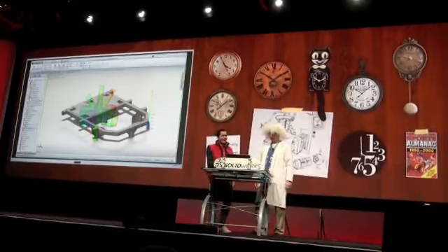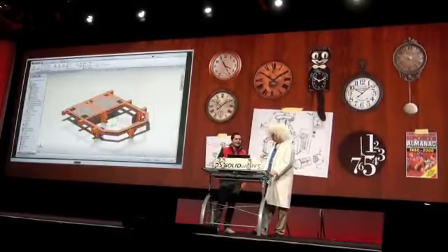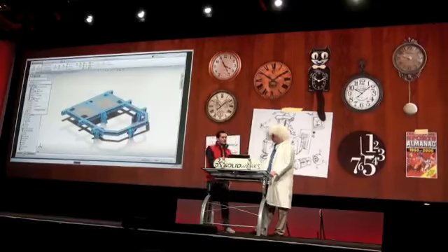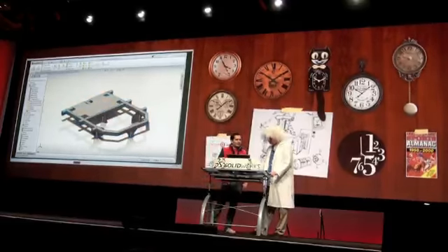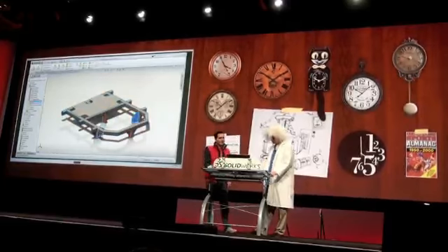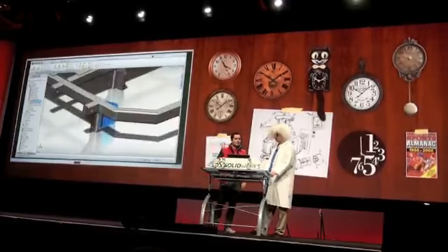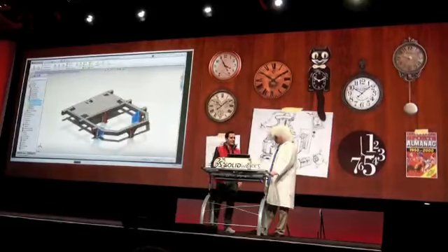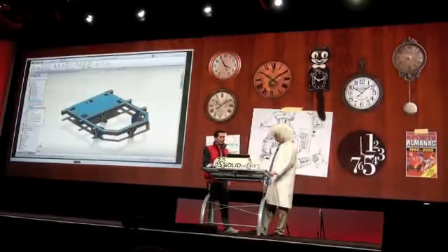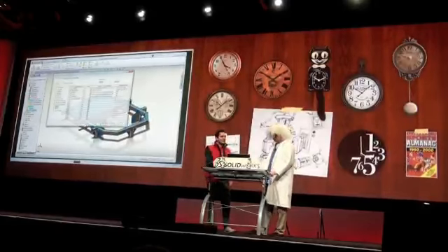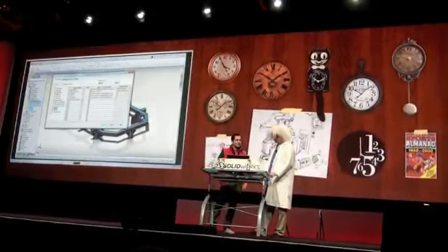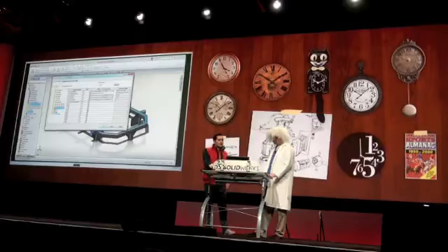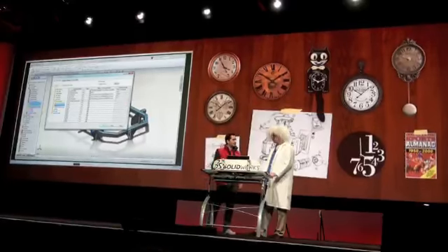You know what, Doc? I looked at this subframe as well, and I saw some pretty cool tools. You know, this cut list automation with a 3D bounding box automatically captures cut list properties, which reduces the time to detail the weldment structures. So description, length, width, and thickness are automatically generated. And we can see that here in the item properties. So for gussets, end caps, you know, the description even includes the dimensions.